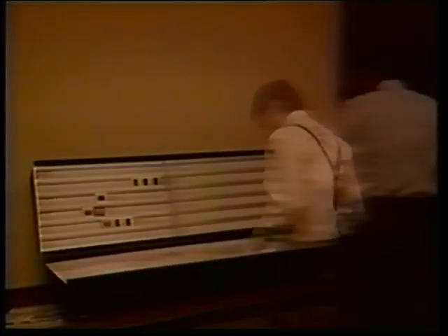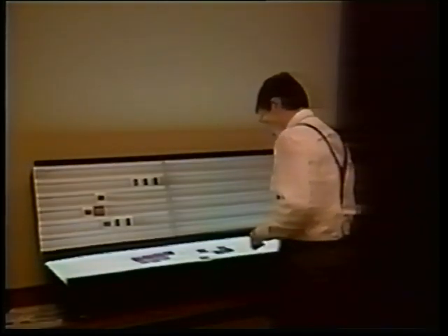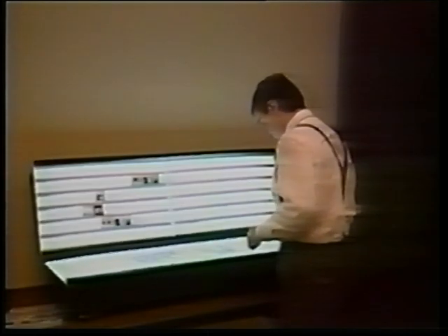The end of life normally comes when there is no longer sufficient emissive material on the electrode coils to start the lamp.